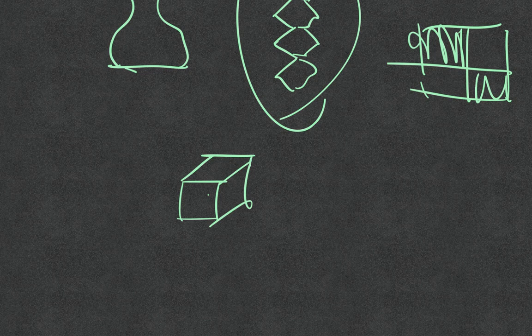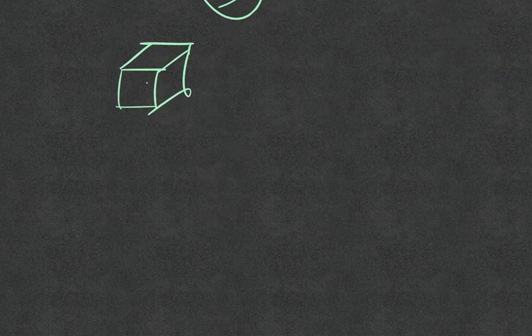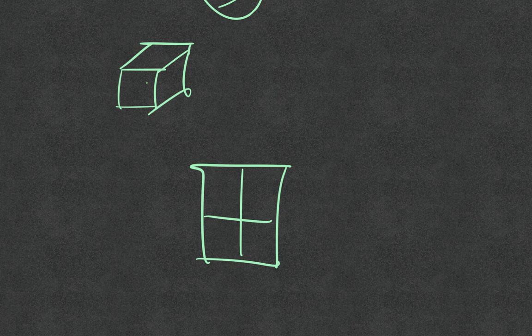Now this doesn't necessarily apply to poromechanics, but you can apply the same idea in poromechanics. By the way, the Taylor-Hood element is also one of the options. You can apply the Taylor-Hood idea to cure the volumetric locking, having the displacement part use a higher order polynomial and the pressure part and the pore pressure part both use a linear element, or at least lower order calculations. So that would also make sense.